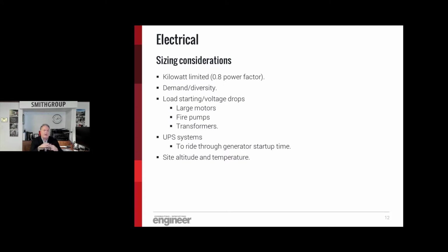The UPS systems in the old days used to have to size the generator 2 or 3 times the size of the UPS. That's because the UPSs were not designed with particularly clean input power. The generators had trouble handling that kind of electronic load. That's really changed. UPSs are much better. You still need to check with your vendor UPS and generator to talk about compatibility. You can model that in the software.